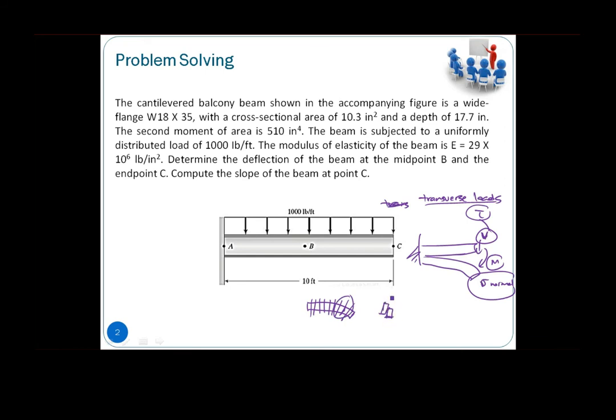You don't have the shearing effects in between this. So that is under Euler-Bernoulli. You won't consider this as shearing effects, whereas under Timoshenko beam theory, this particular effect comes in.